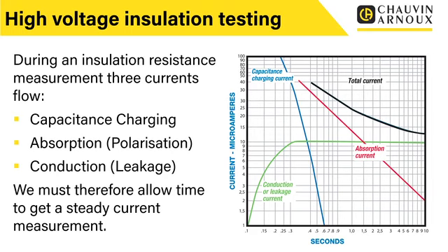So that again is a current flow, but this isn't due to anything to do with the quality of the insulation. This is just a fact. It's based on the insulation, and it does change depending on what insulation medium you've got. So what material you're using, this will take longer or less time, and again, the thickness of the insulation and the cross-sectional area and all these things will affect this. But it isn't to do with the condition of the insulation as such. This is just a fact of any insulation, whether it's new, old, damaged or not. You will have this absorption current that will flow for a period of time.